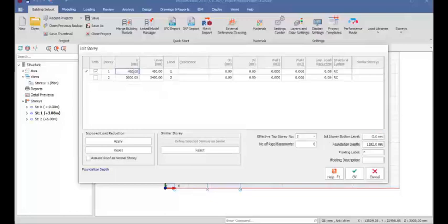So this is going to be our story level, which is story 1. The 450 is just like from the surface of the earth to the floor of the portal frame structure. While this 3000 is supposed to be the height, and then we make it 4500, because we are considering designing maybe a workshop or a warehouse. It can be used for any of those purposes.